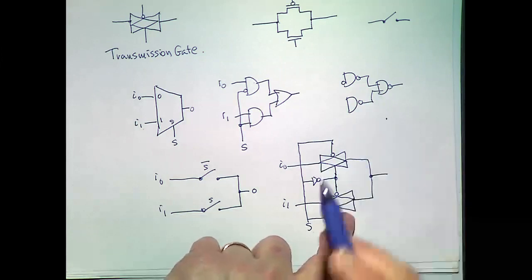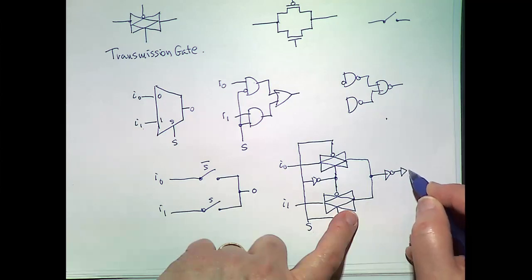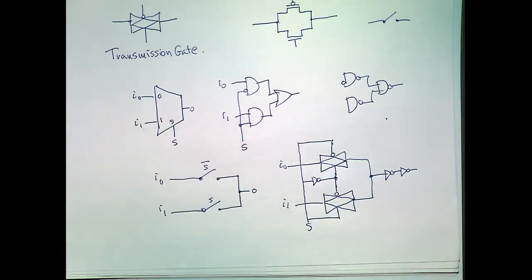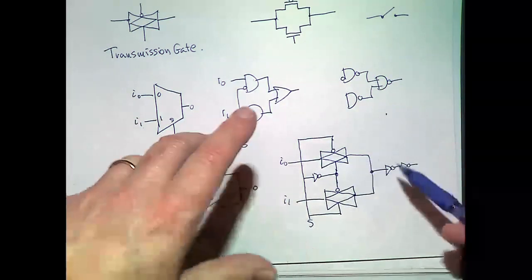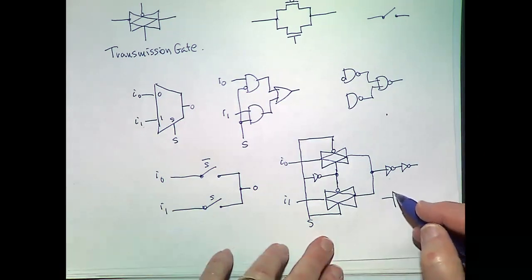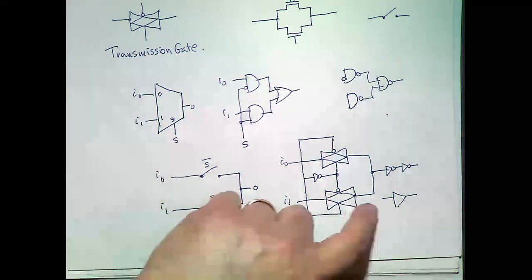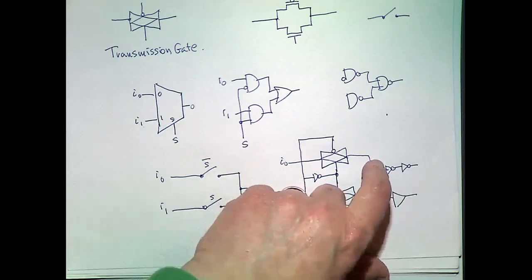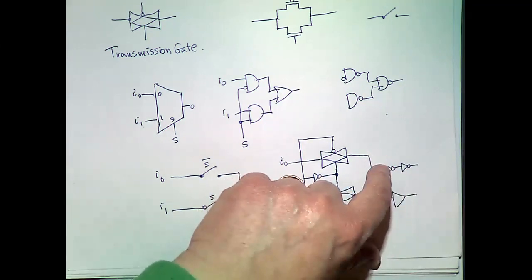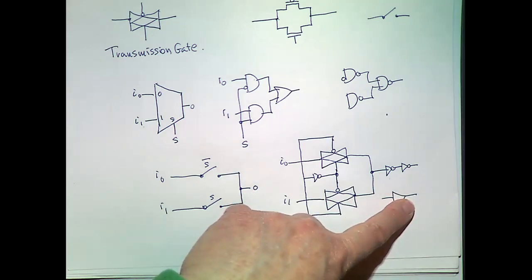Okay. So let's say you want an apples and apples comparison. Then basically what you would do is you would just put two inverters here. And so now we have 4. So it's 14 versus 10. Still, this is better. Okay, so you can always just put two inverters. And sometimes in your circuit, you'll see this, and you'll say, why is that there? What does it do? So it may, in fact, have some use in, I guess, conditioning the signal, improving its strength.